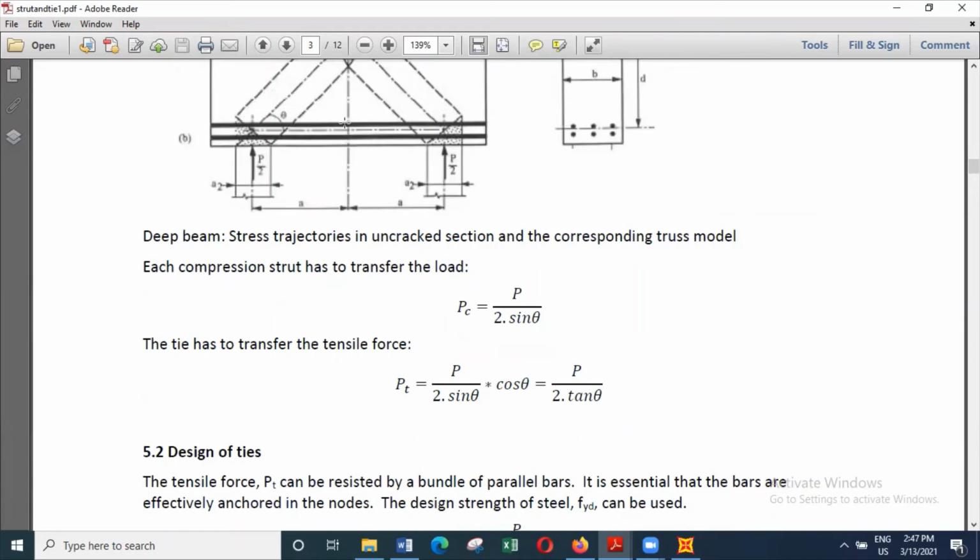And the other important thing is, this reinforcement should not be concentrated. We can distribute the reinforcement. So the reinforcement required can be provided in multiple layers. And also if the depth of the beam is about 0.6 meters, then you can actually spread the reinforcement in the bottom 10% height of the wall. So generally, when you consider the bottom 10%, because the wall height is 6 meters, you get 600 millimeters.